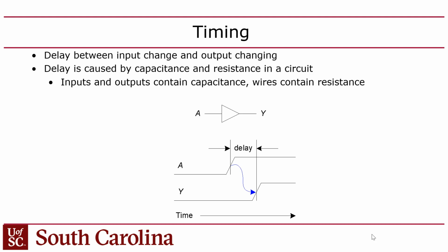And that time is generally just the resistance times the capacitance. Believe it or not. It seems too simple, right? The time in seconds is the resistance in ohms times the capacitance in farads. It just happens when you multiply those two, you get seconds. Crazy, right? It seems too simple to be true, but that's literally what it is. It's the RC constant.